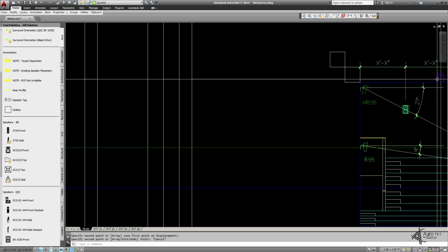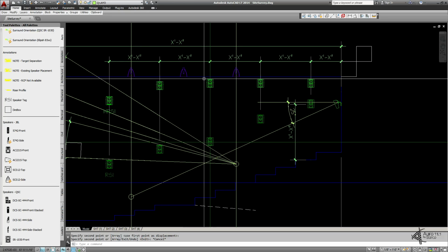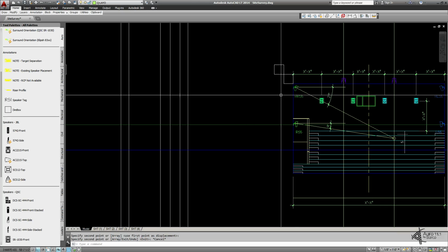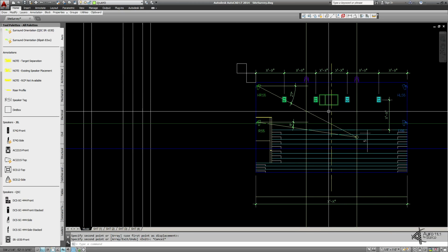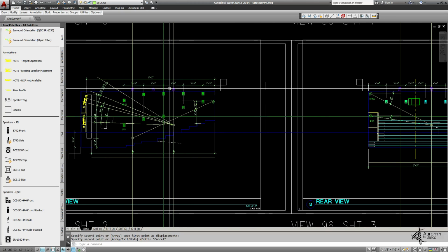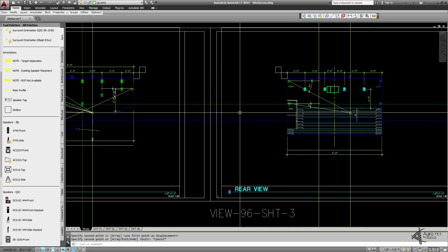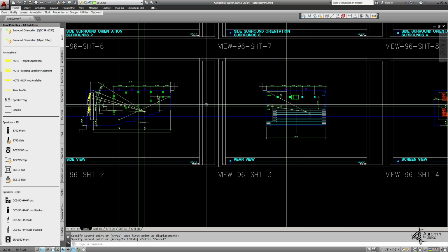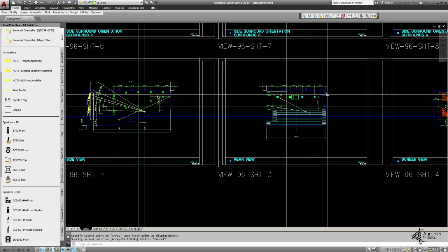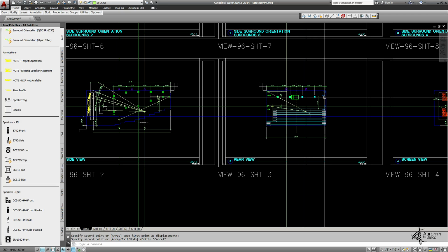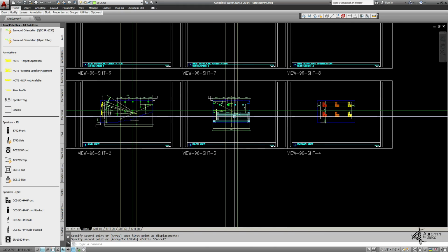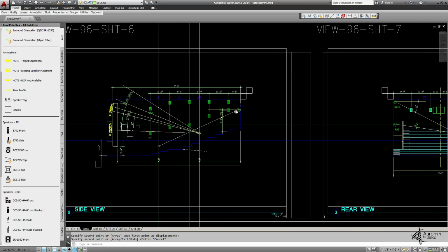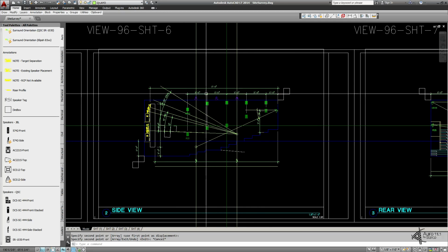So our U bracket for hanging it is twisted between the two. So in this auditorium we would have 6 speaker locations, and then of course reflect those onto your reflected ceiling plan, and then you can avoid any lighting or HVAC ducts.